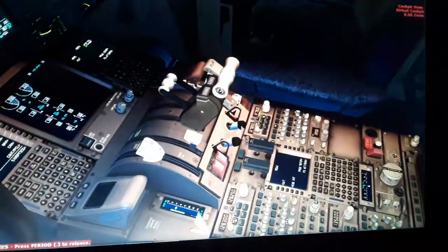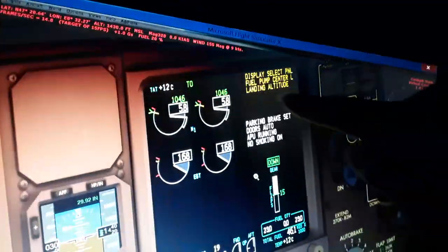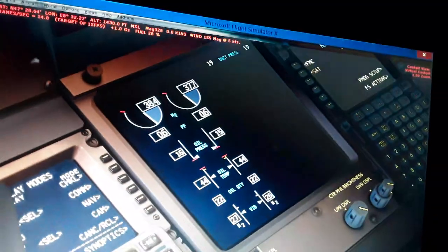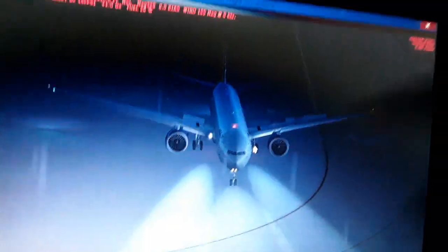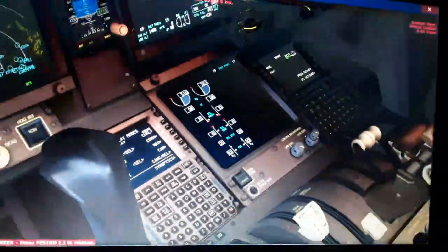So we need only to use the fuel flow back to be on, both these switches, left and right, and we're gonna have engine shut down. Now we're gonna have the fuel flow on. You can see here both engines, the right and the left, and the spinner is spinning faster because we have fuel flow to the engine. So this is all for the engine start.